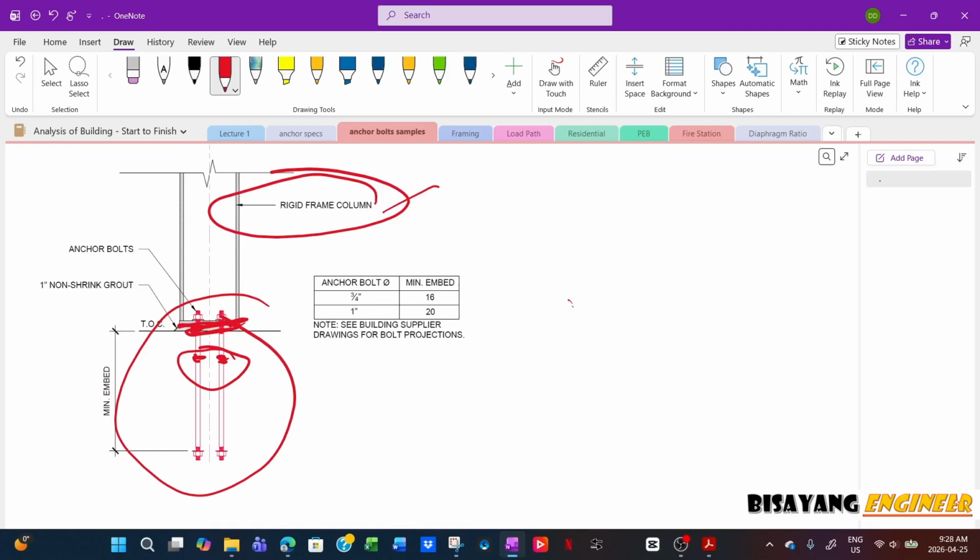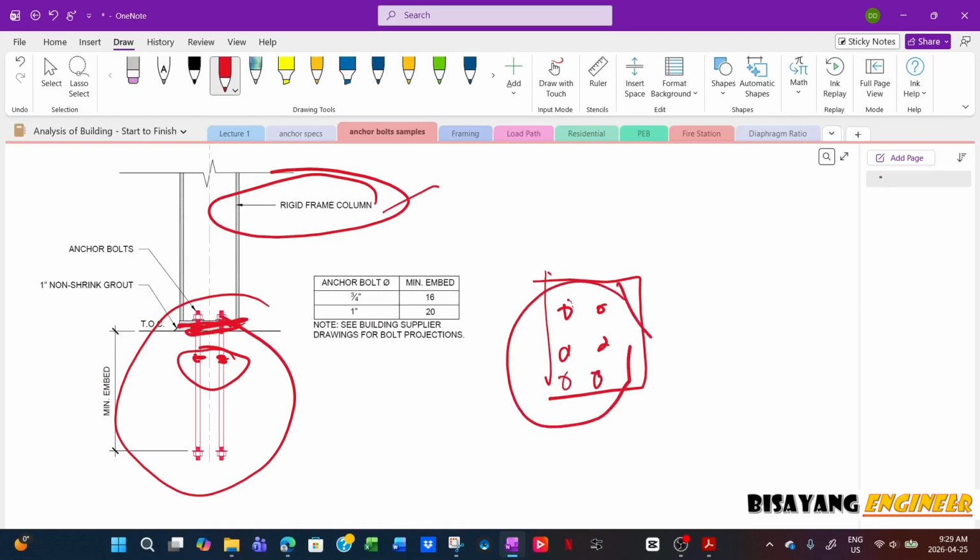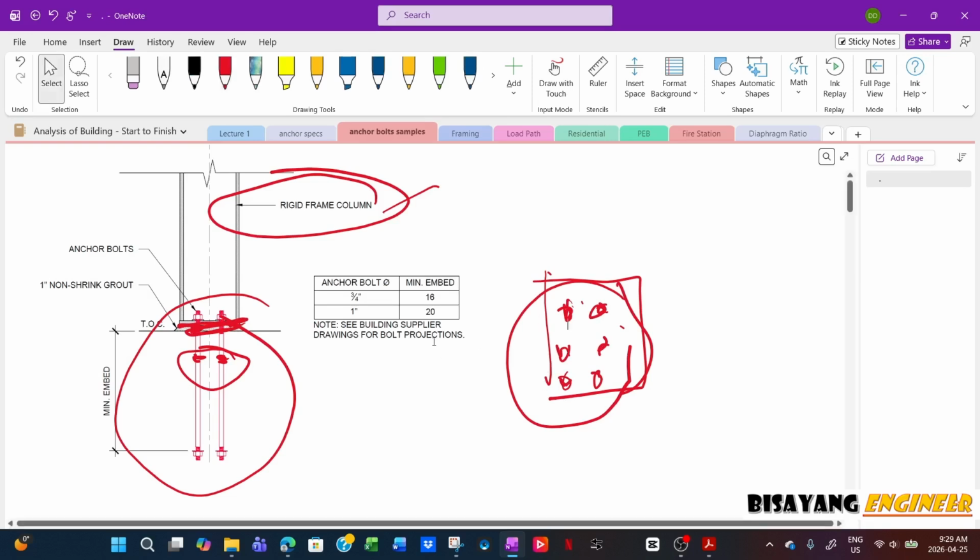So they already dictated how many bolts, and most of the time they use the minimum, which is 4. Although the horizontal load is really small, they always use 4 bolts. And then in large span regional buildings, sometimes they will use 6. The most I saw was 6, and the minimum is 4 per OSHA, which is a standard minimum requirement.